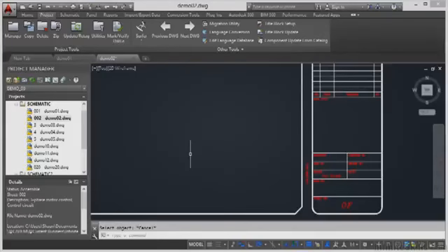But there's nothing to stop you picking information from an existing AutoCAD Electrical drawing. Title block text is a prime example because it's normally descriptive. And if you want to add that to your description field, why type it again? Just click on pick it in the title block, and it'll add that text to the description field in your AutoCAD Electrical drawing. A neat little tool, again, that saves time, makes you that little bit more productive in AutoCAD Electrical.